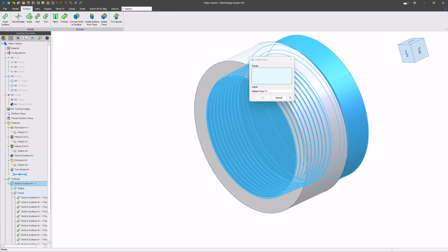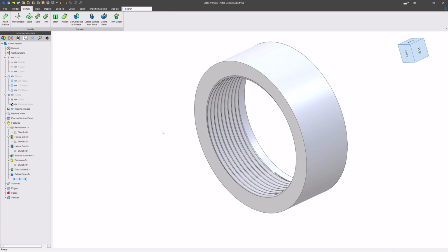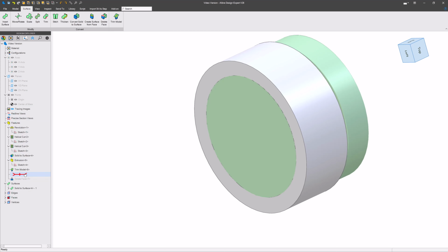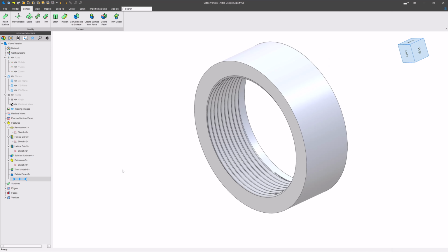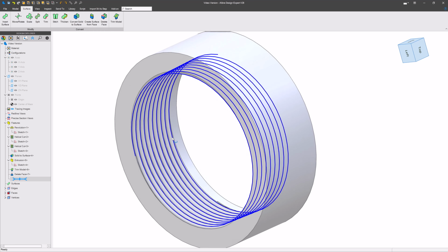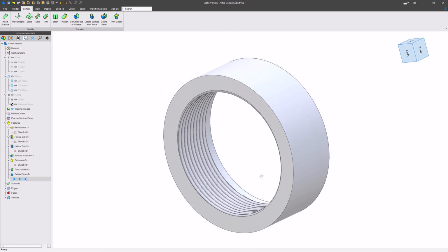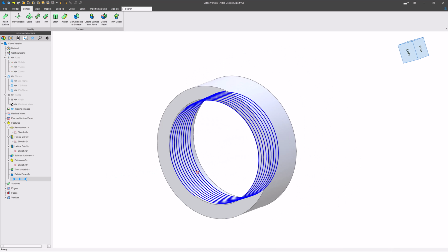So if I really want to get rid of it, the benefit to deleting every face is that if I have a workflow that has 8 different surfaces and you don't want to get them all confused, then you can get rid of surfaces as they're done so that you can just run through your tree and keep your surfaces a little bit more straight. So I'm one to delete face on surfaces, but it's a lot of extra processing that isn't necessary, and you can rightfully just hide your surface to save a lot of things. Okay.